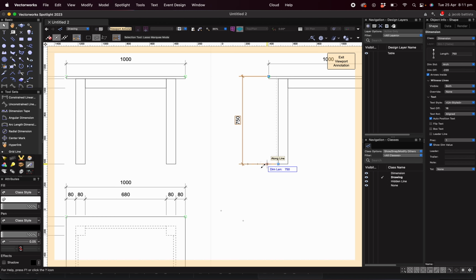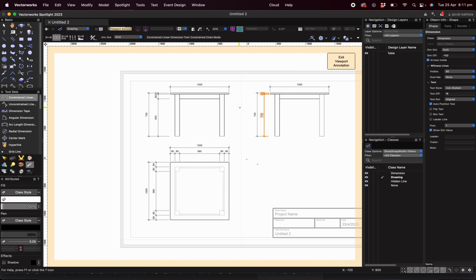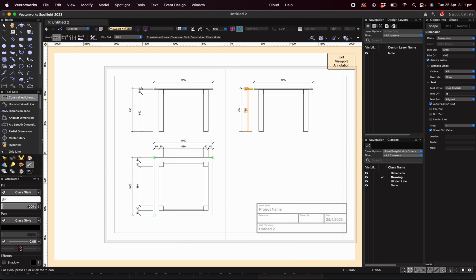So just make sure you're aware as you go what the dimensions should be. So the other chain dimension I'm going to give is just without that little frame section, just so the builder doesn't have to do the maths to work out the height of the leg. This is looking good. It's only missing one thing, which is some text to say what they are.